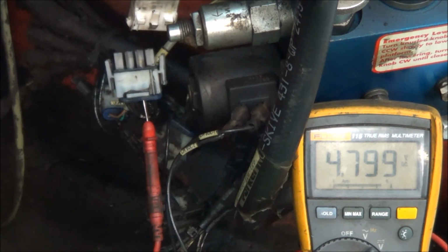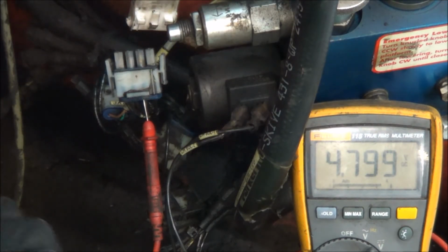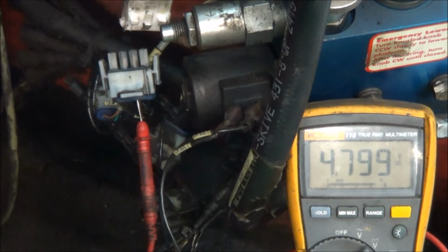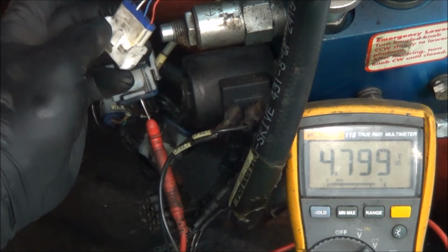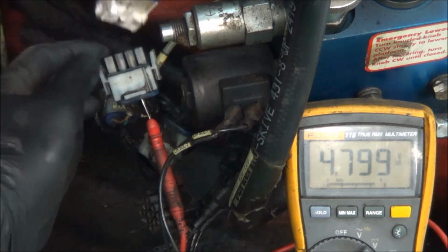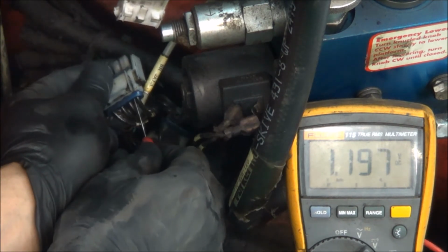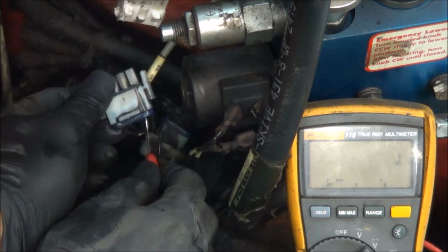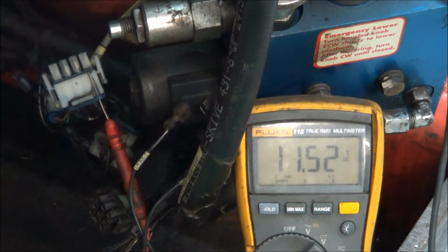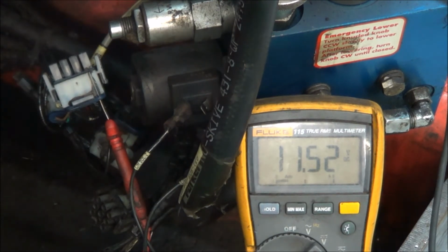So for this reading, I was hooking up my black lead on my meter into the negative, battery negative. Alright, so let us test now the negative part of this, the negative supply. I know there's already a positive supply on this, but you know what, let's just test it out. So okay, 12 volt supply is good. Okay, one last part to do. Integrity of my wires leading to the computer.